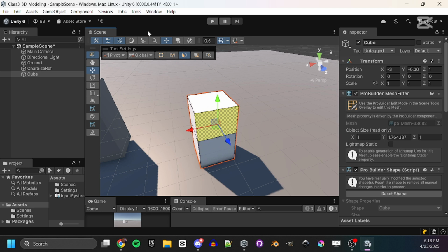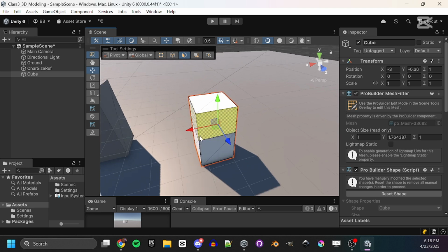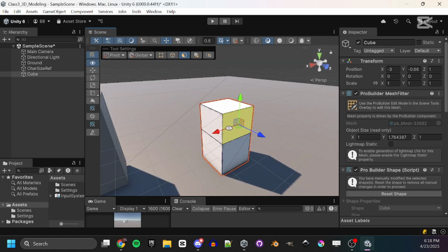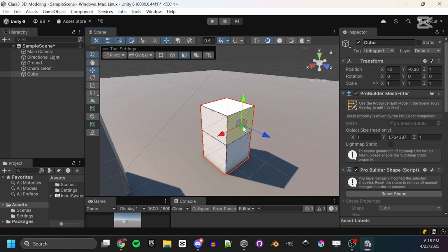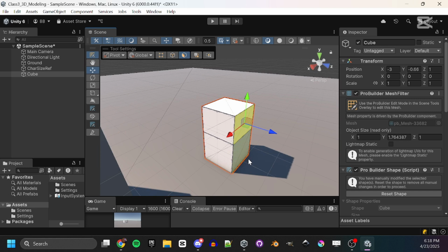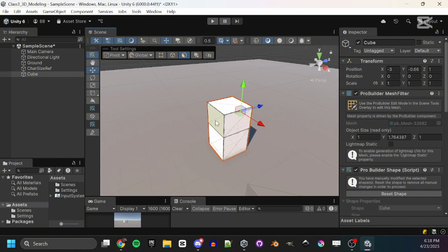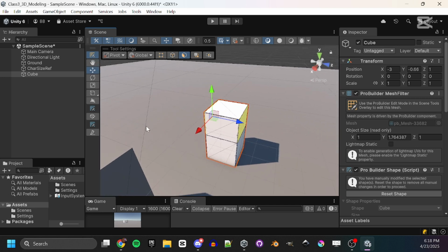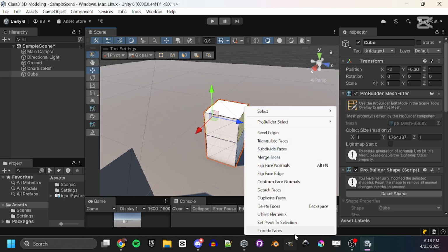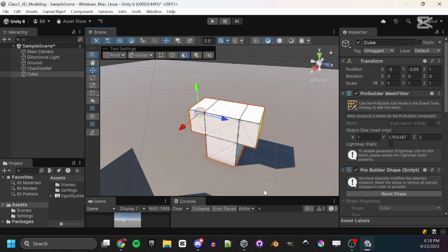It can be a little bit easier to tell, for example, if we turn on this mode here, draw modes, and set shaded wireframe, because then we'll see that these are actually two separate faces. So now I can operate on them differently. So if I were to select this face over here, control select that face over there, and then extrude again, all right, now I've got two arms.